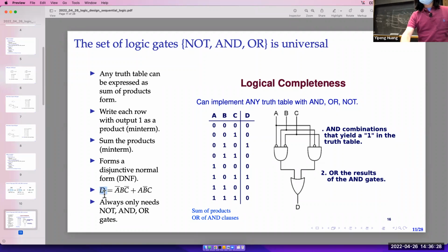So this function here, D, subject to inputs A, B, and C. A, B, and C are all Boolean, right? If the D function is this expression here, well, this expression right now is put in a sum of products form, right? It's an OR connecting together two ANDs, A and B and C, and B and C, like so.